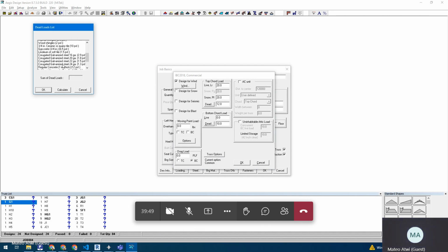Now, if you click on it, that gives you the ability to say, hey, we're going to use these materials, and it would give you a dead load from that. If they don't call it out, you could go through it, and it pulls the information. We entered it based on the ASCE book that gets distributed.